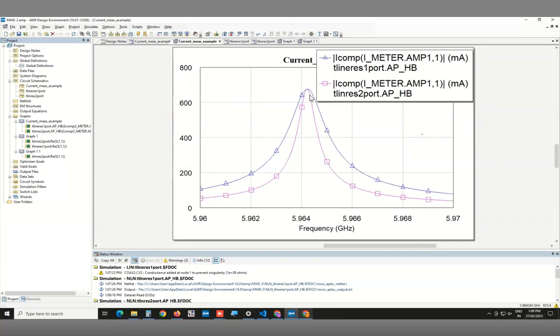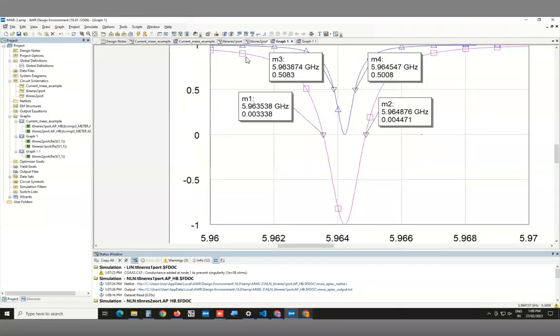Okay, so again, you see the resonance is at the same place. Why is the resonance the same? Because we have already adjusted the capacitance of the single port circuit to match. So you see it's peaked at the same value. You also see this a lot more clearly, that this is narrower. The 2-port one was narrower, so a sharper resonance, which means a higher Q, as we interpreted from these graphs as well. So you're seeing the same thing here.